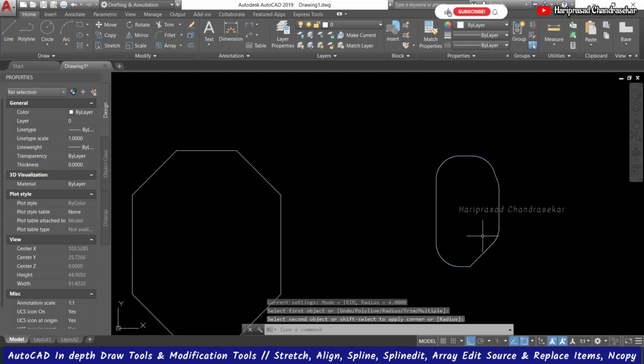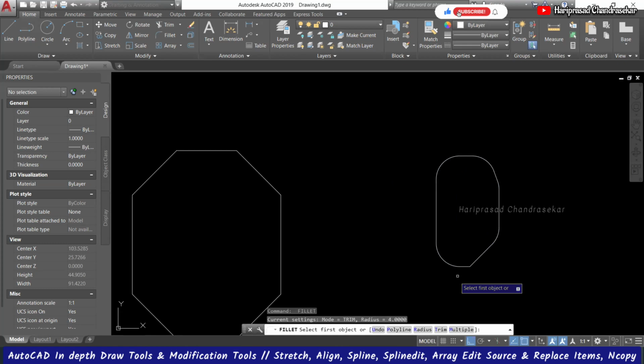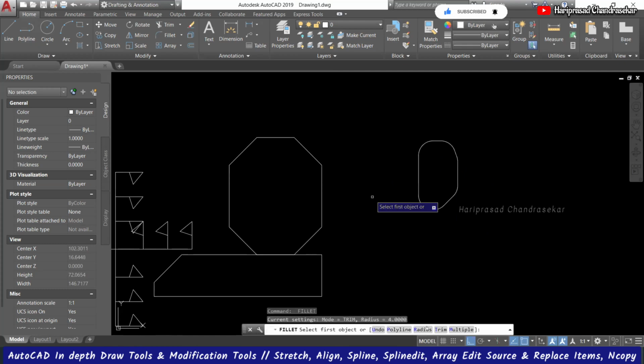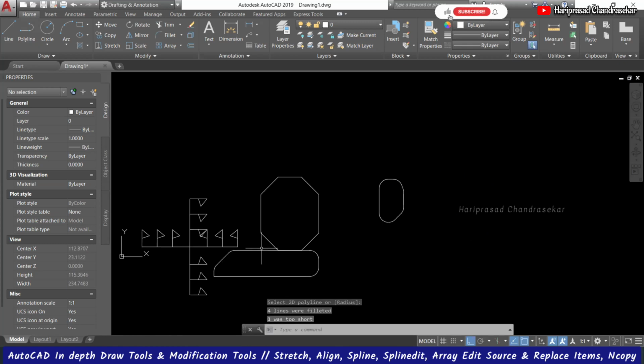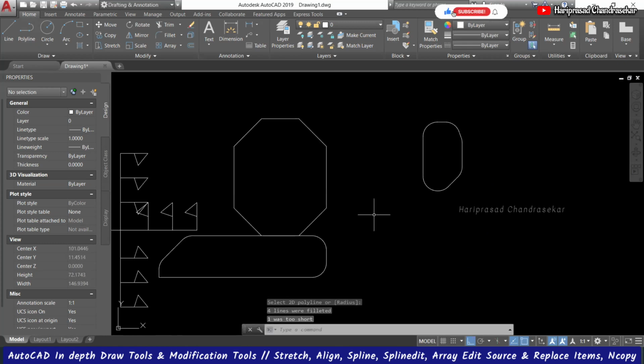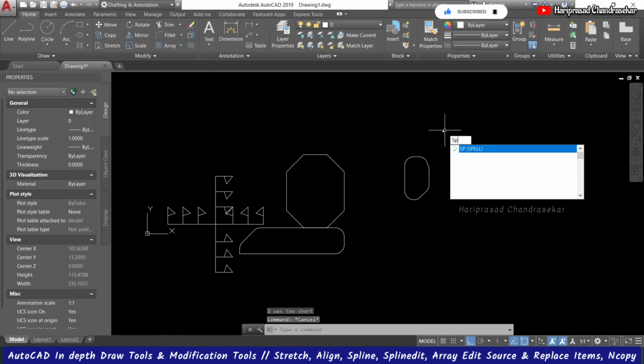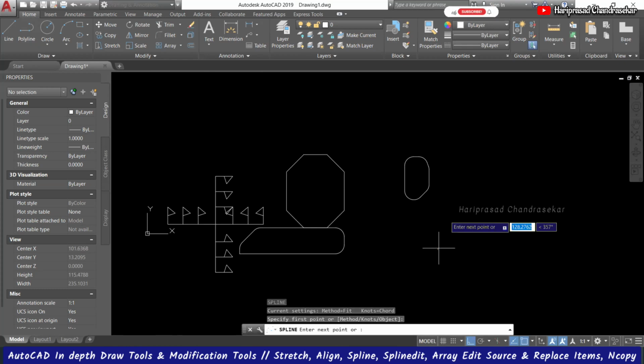So one by one we are doing now. We can also select polyline so that wherever you have a sharp corner, it will be filleted. If I'm going for a radius and also polyline and I'm selecting this, see all corners getting filleted with the 4. Okay, this is fillet, chamfer and all. Okay, if you have curves, there is something, the blend curves option.